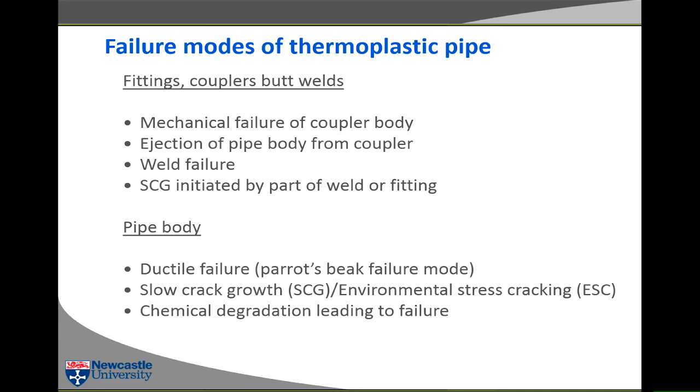It turned out with polythene, the worst material for producing slow crack growth is actually detergent-like materials, which is a real pity because the other application for plastic pipes in the 1950s and 1960s was washing up bowls. And actually detergent is the worst thing. The main tests for slow crack growth on polyethylene still use detergent as the sensitizing fluid.